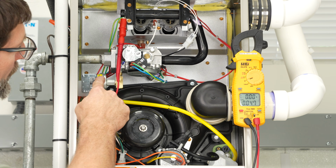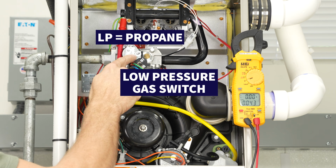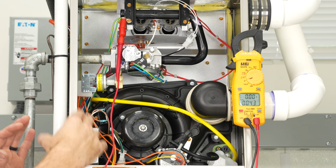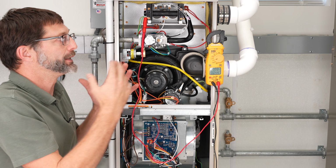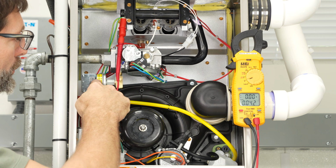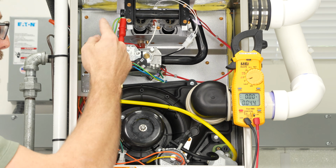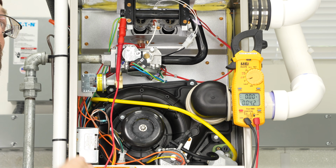Now, one thing I want to point out is on this furnace, we're equipped with a low pressure gas switch, and that means that this has been converted to propane because it's LP. So right here, this is protecting the furnace in case you have low pressure at the outdoor propane tank, because you don't want a low pressure on the outlet because you'd have an intermittent kind of flame, or it would just not be correct. And so that would be a problem. So this right here could be opened up right now, and so that could be the issue and maybe not the pressure switch. I've seen these installed on limit switches, so basically in series breaking the limit switch wires, or on the pressure switches like this, so you want to be aware of that.